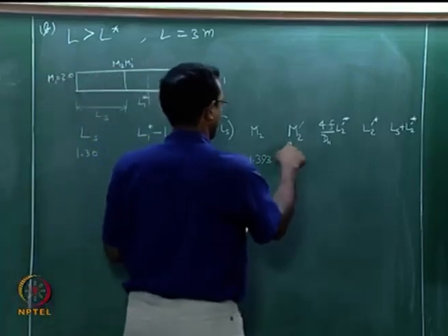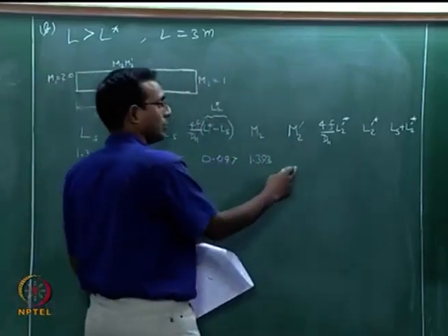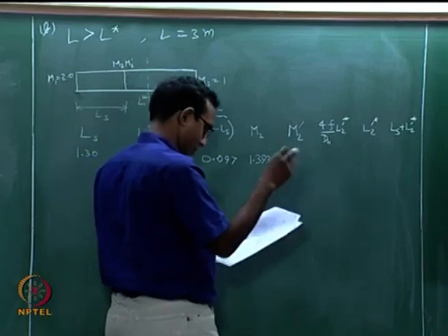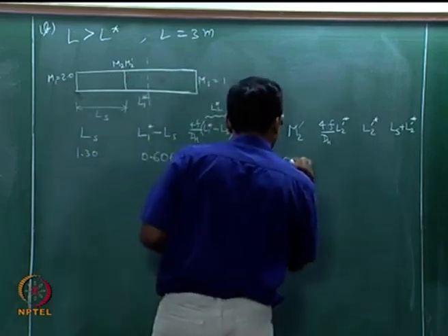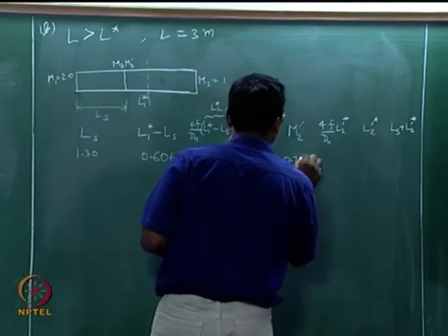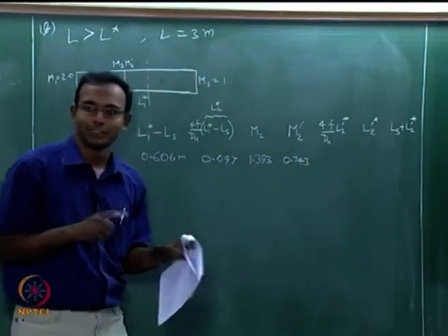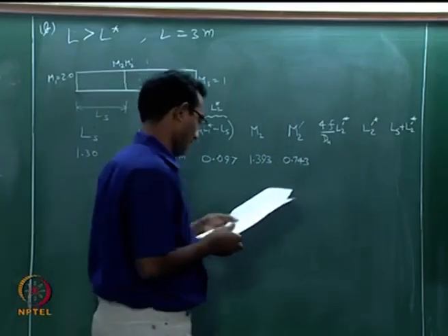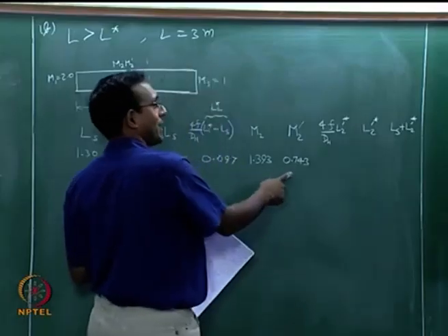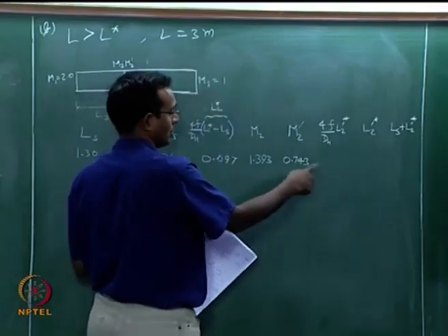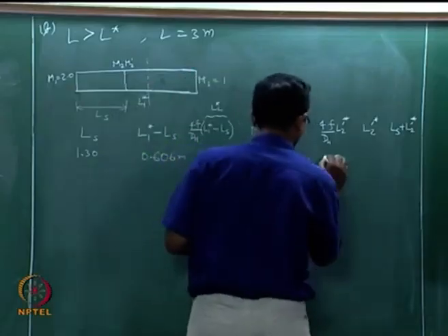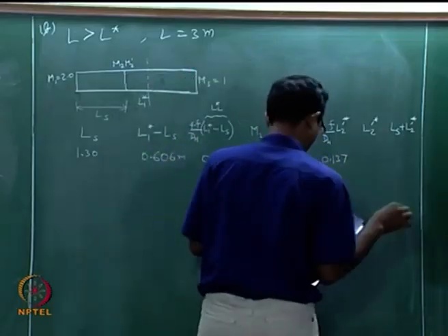and M2 prime I am now going to normal shock tables across these two columns alone, 0.743. Again remember, in normal shock tables, when you are flipping pages you should go to the correct gamma tables. Now I will go back to Fanno flow tables from here to the next one, that number is 0.137.